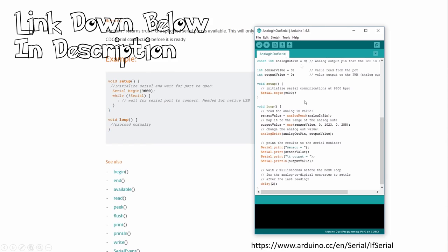Okay, so I'm sure that most of you are very familiar with this code. If we want to send something to the device, and as you know, UART is also known as serial comms, we can send ASCII code to and from our device. Now ASCII stands for American Standard Code for Information Interchange. So if we open up our serial terminal over here, our terminal will print sensor as well as the sensor value, and we can specify to print out almost anything that we want. These are some of the functions that we can use for our UART bus. It's very simple and very fun to debug using serial. If you want to check out this code, check out the link down below.